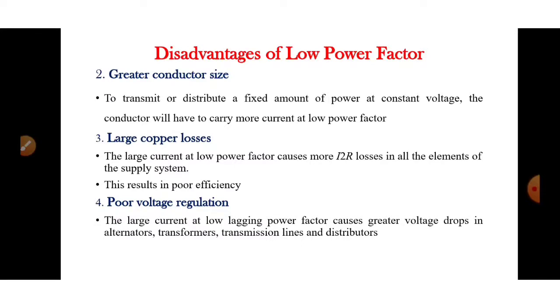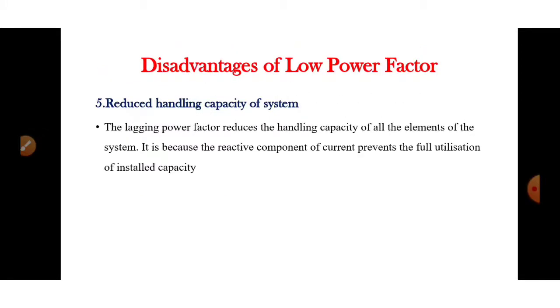So in order to eliminate these problems, we have to improve the power factor, or we have to maintain power factor closer to unity. And the last one is reduced handling capacity. That is, we cannot operate the equipments in its installed capacity. So the lagging power factor reduces the handling capacity.